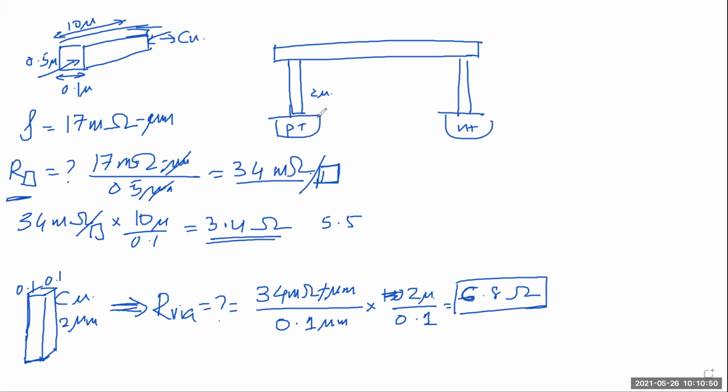So yesterday, remember, we connected metal one, via, metal one, and tungsten via. We calculated the source to source end. So basically we had a PMOS, and this was one via, the total wire resistance. So this was R via, R wire, and then obviously the second via, and then you had the source of the NMOS.